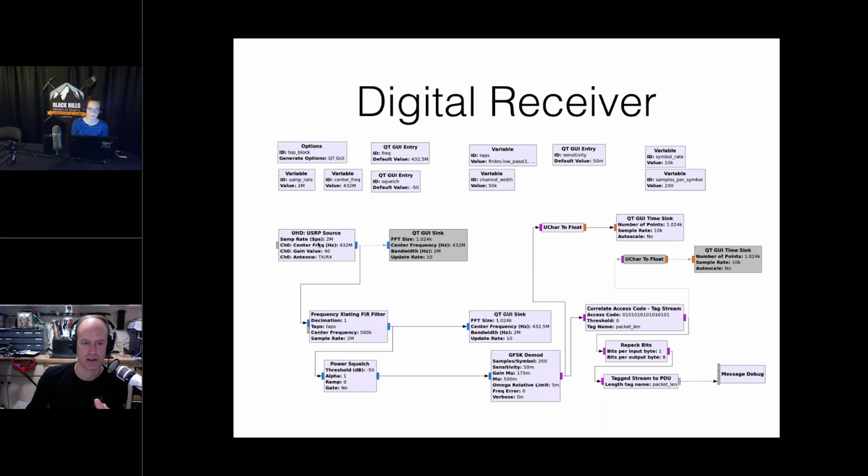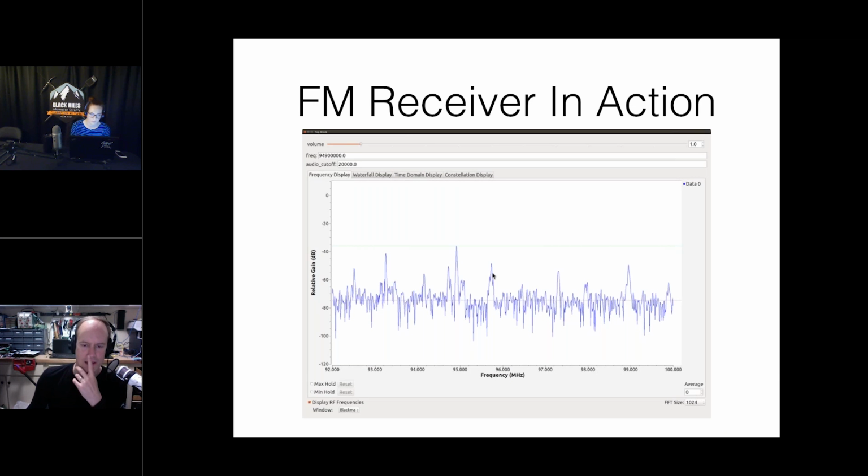You've got the SDR that is set up to bring data into the flow graph. We talked about that in the other FM flow graph as well. We've got this filter, called a FIR translating filter, but ultimately all that block does is it tunes, or centers in on, let's say, this peak. If we type in the right number, it'll go to this peak right here, and then it'll use a filter to keep all the stuff close to that peak,